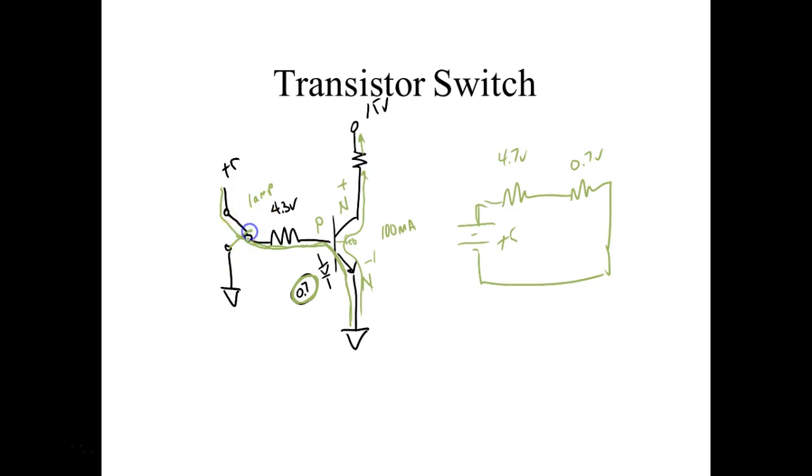Now, if I come over and switch this down right there, this and this are connected together. My base current goes to 0 milliamps. If my base current goes to 0 milliamps, then the transistor is going to turn off. So it's going to act like an open switch. We're going to show y'all guys, we use this saturated switch all the time. We call it a saturated switch, but actually we're switching it between what? Cutoff and saturation.